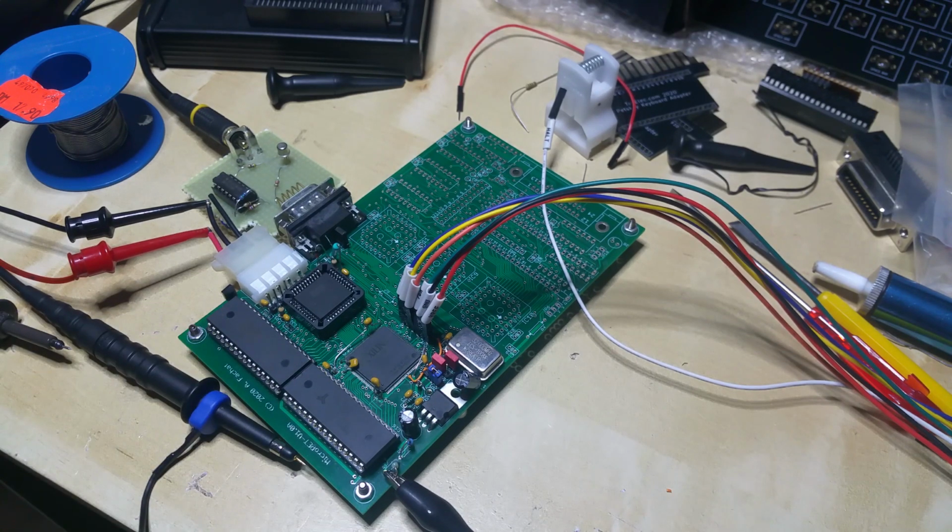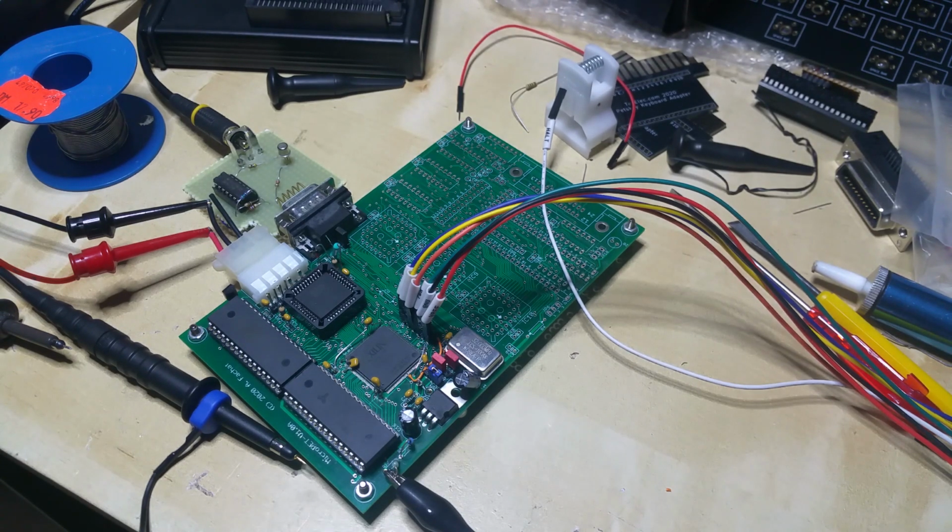There are serial ROMs with an SPI interface, and I have to be evaluating if the CPLD has enough resources left to be able to create an SPI interface for that serial ROM, and also, because otherwise there's no ROM, no code that the CPU can execute, how to basically load some code from that serial flash ROM into RAM for the CPU to execute. So those are the 3 options that I'm looking at.